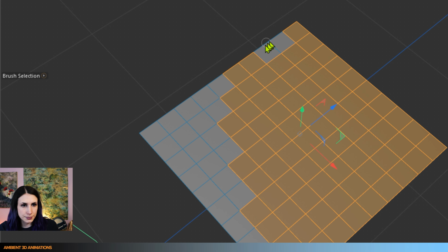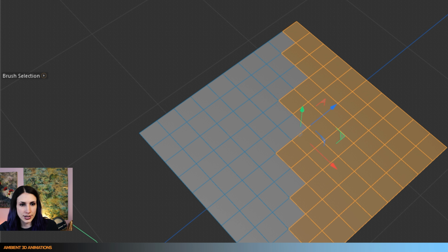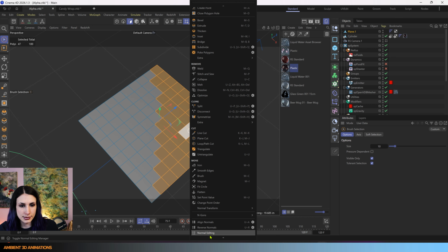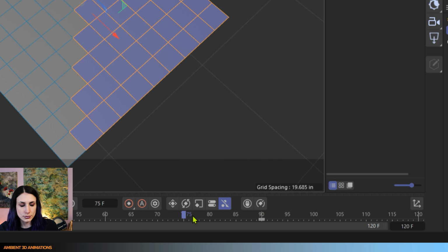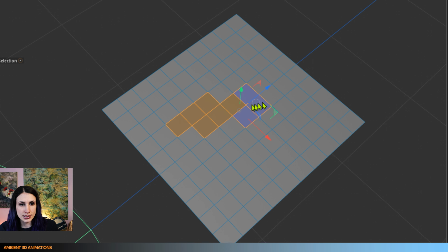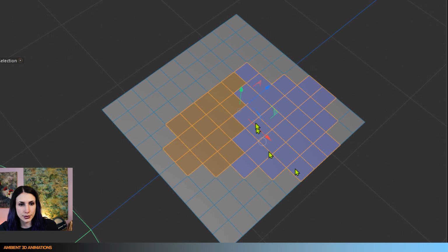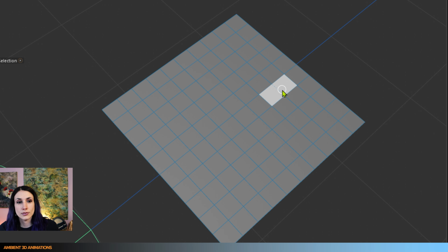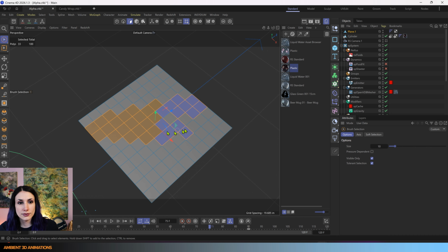Now, a common problem that people run into while 3D modeling, and this even happens for professionals from time to time, is they'll accidentally flip the normals a direction. So I'm going to right click on this, and I'm going to click reverse normals. And that'll actually switch them. Now you can see that some are facing forwards and some are facing backwards. So this can affect how materials are calculated, what's the back side and what's the front side of an object. And it can in fact affect alphas.